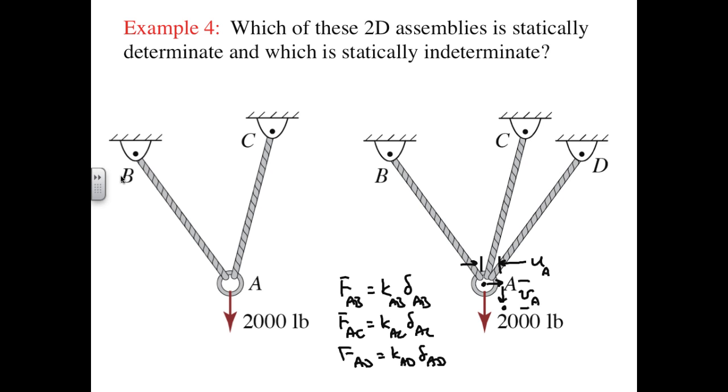We can then ask if those forces obey the component equilibrium equations. If yes, we have our solution. If no, we reposition the displacements u and v so that the member forces do satisfy equilibrium.